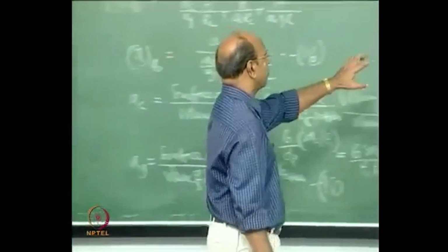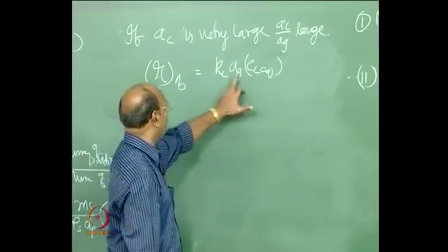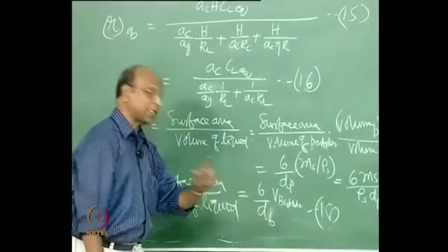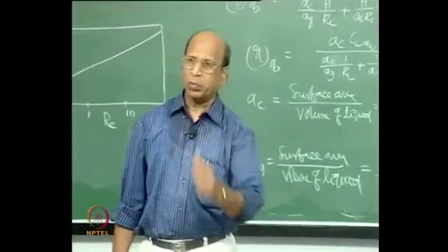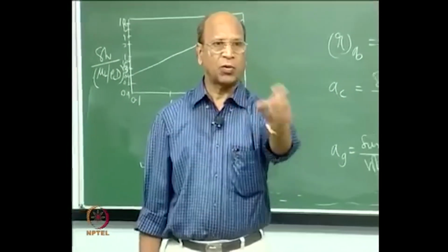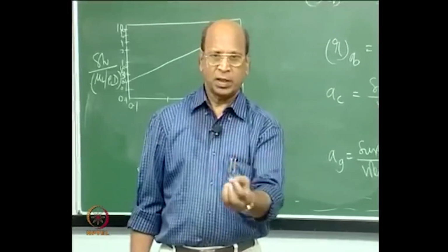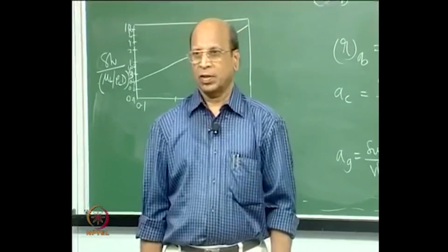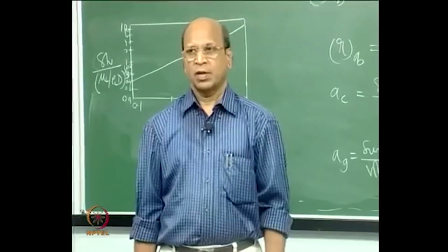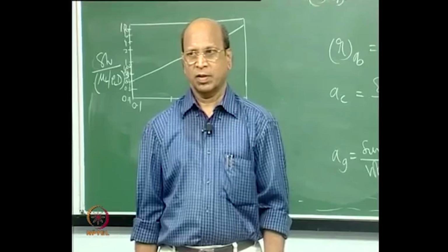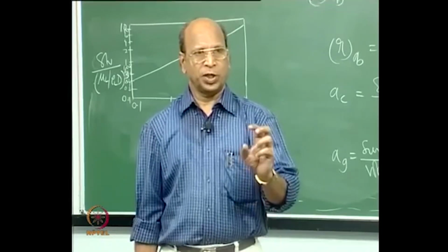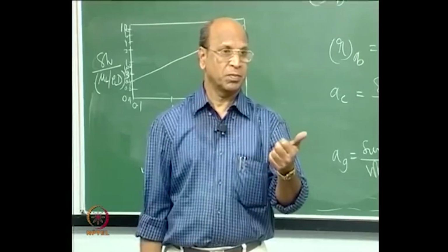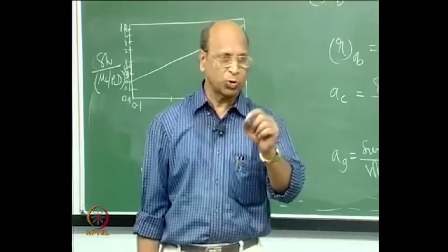So, when I want to use this equation, all my focus is only Ag, but Ag now depends on dB, and how accurately I measure dB is important thing for me. How do you measure bubbles in slurry? If I ask you in aquarium you have fish is moving, but gas bubbles also are moving. If I ask you to find out what is the diameter of that, how do you find out? Bubble free volume, we subtract that with the volume. Yeah, that is the most engineering way of doing things, but what is the assumption? All the bubbles are same, okay, bubble size, but clearly you know that the bubbles are not same.